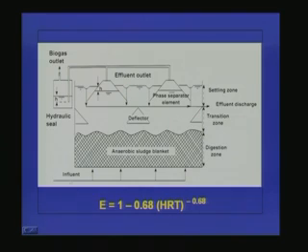It will be entering the reactor at different ports, and you will have an anaerobic sludge blanket. That means a thick flocculent sludge blanket will be available in the reactor. The wastewater will be entering the anaerobic sludge blanket through the influent distribution pipes. So what will happen? The wastewater will be passing through this anaerobic sludge blanket.